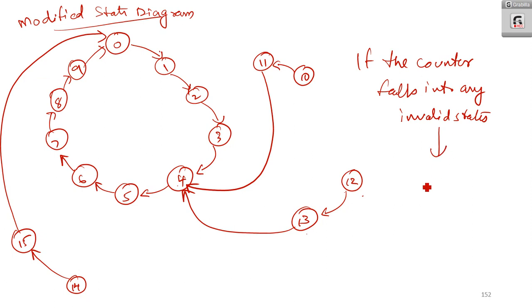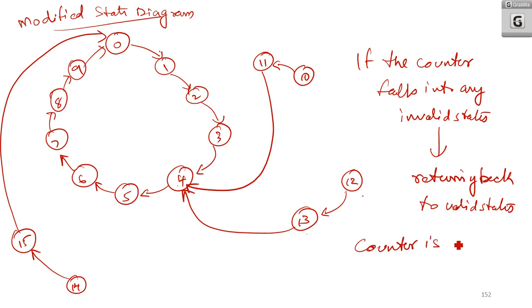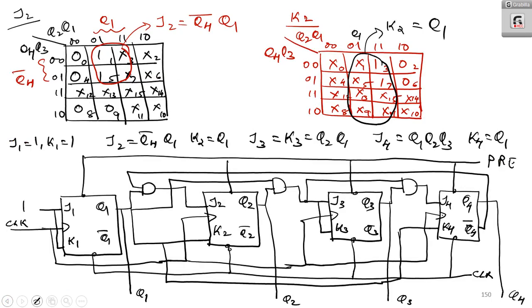Then it is returning back to valid states. Therefore, what we can say? Therefore, we can say that the counter is self-starting.